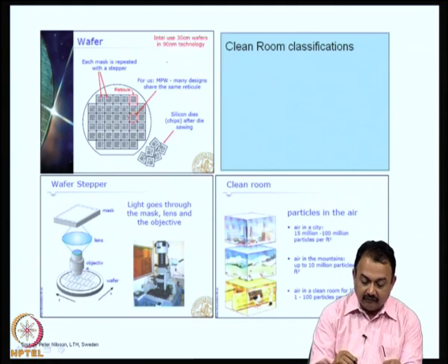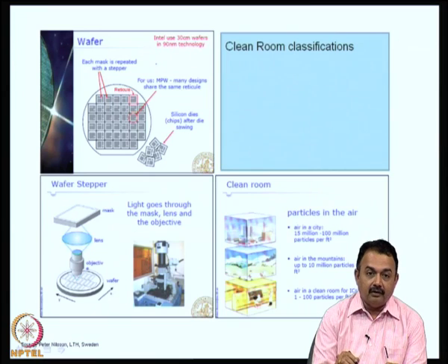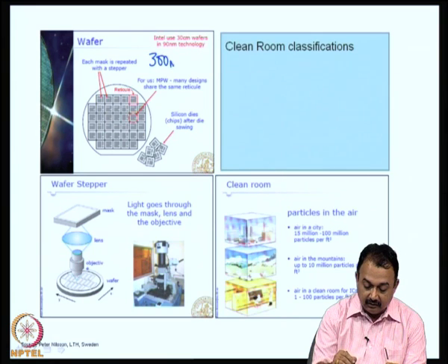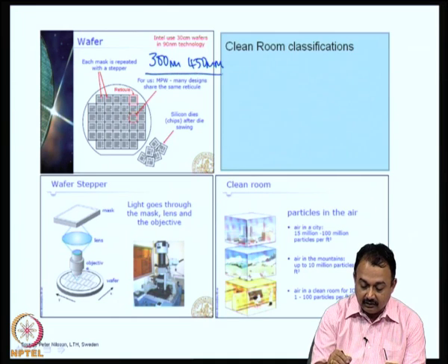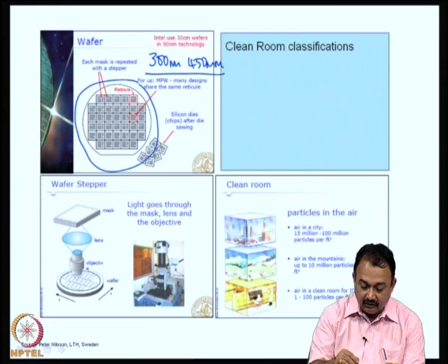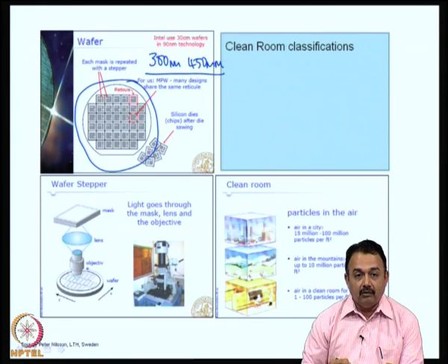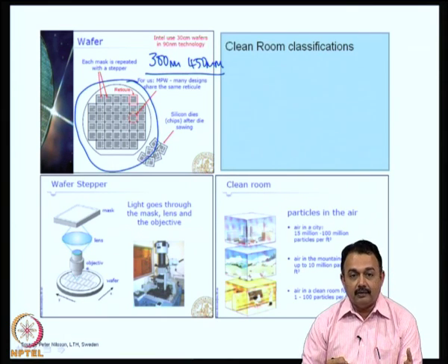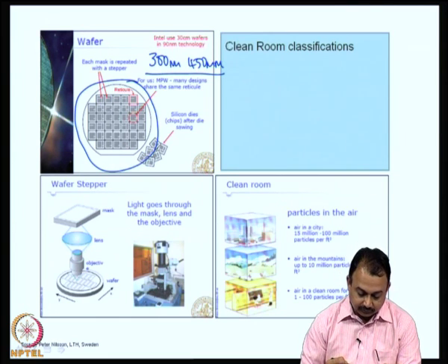So, the various sizes of wafers are dependent on the number of dies that have to be generated. Today we are working at 300 millimeters, and 450 millimeter technology is also well established. As the wafer sizes increase, you are expected to get more yield out of it and more dies coming out from the fabrication process. But at the same time, the die size can also increase because you are increasing the density of the interconnections.